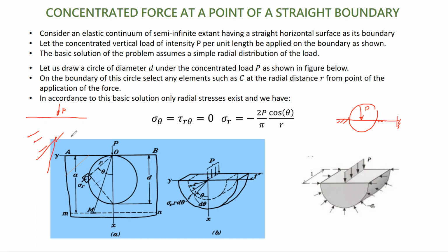The problem is a two-dimensional problem, so we don't look into the thickness. But for the sake of understanding, this concentrated load means a uniformly distributed load through the thickness, as shown. Assume in the formulation of the problem that the thickness is equal to 1 unit, or better, that the thickness is constant. Two-dimensional problem.